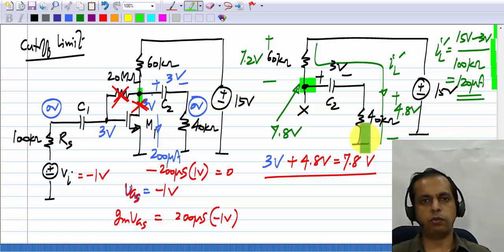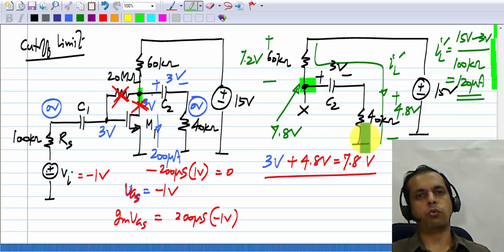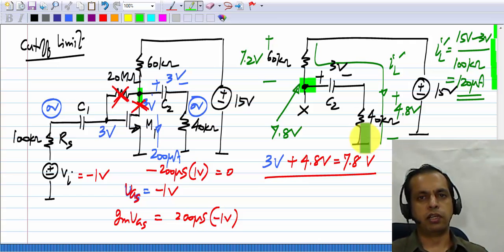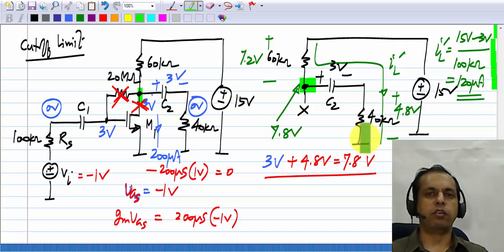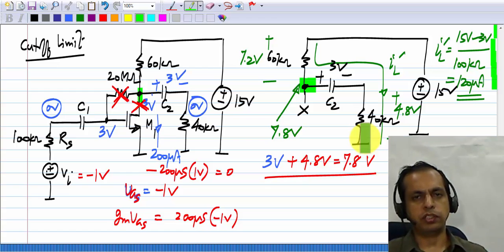The procedure is always exactly the same. You find the total VDS, total VGS, or total VD and total VG, whichever is more convenient for your comparison, and also the total drain current ID. How do you obtain the total quantities? You add the operating point quantities to incremental quantities. The incremental quantities are obtained from small signal incremental analysis, which is linear. And then once you have all of these things, you apply the limits. VDS must be more than VGS minus VT and ID total must be more than 0, and you get the two limits for the signal.